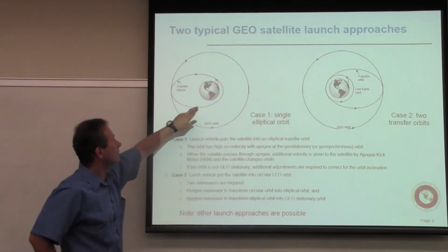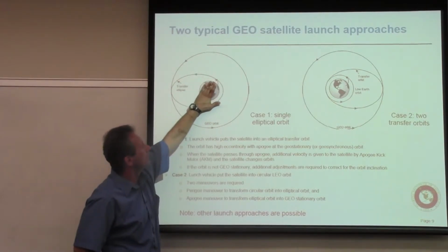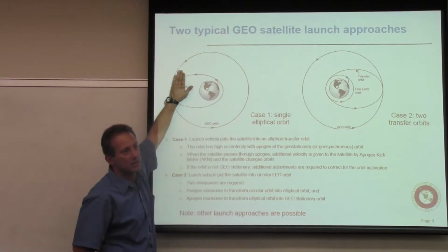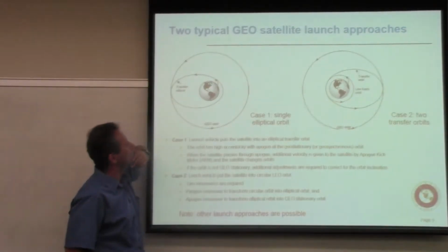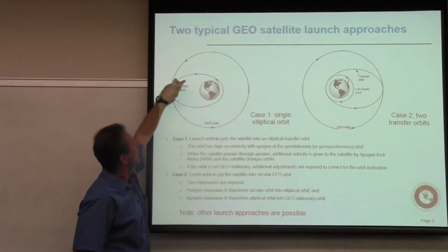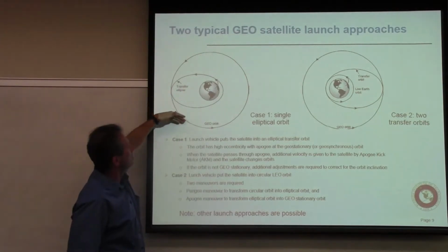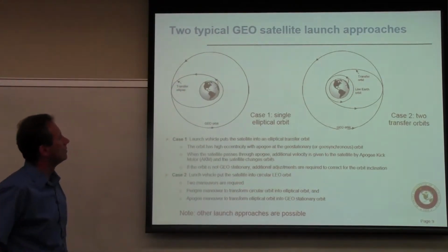So you plan your launch so that at this point in space you're at this height and a given velocity. At this point you turn off the engines and let the satellite ride, usually 1 or 2 times in this orbit. And then when the time is right, you kick in additional boost and you put it in a geostationary orbit.